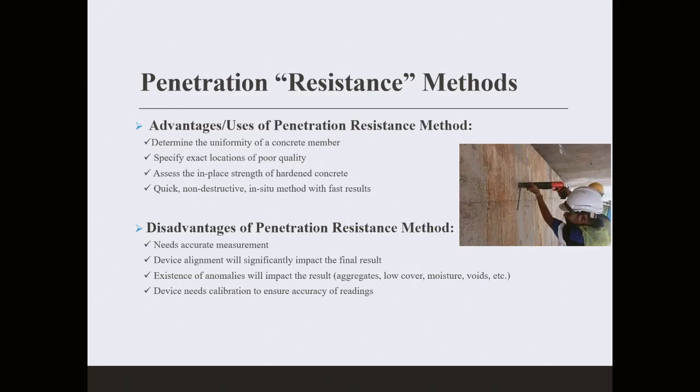Both technically would give you the same results. More or less, the penetration resistance method is used more for the detection of uniformity. And again, here I'm talking about rigid pavement, and about a reinforced concrete section in a bridge project.